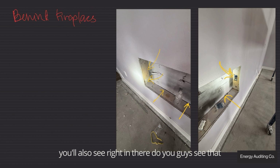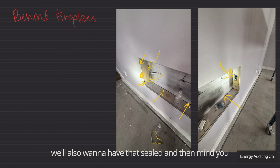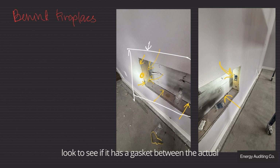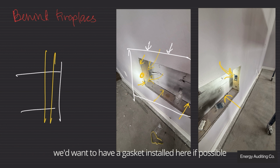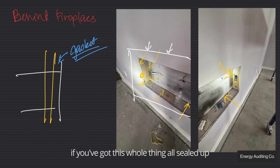You'll also see right in there, do you guys see that? Where those two materials meet, where the drywall meets the framing, we'll also want to have that sealed. Mind you, they're going to lay an entire fireplace over this thing. Look to see if it has a gasket; the fireplace probably looks something like that, and let's say our wall looks like this. We'd want to have a gasket installed here, if possible, if it comes with the unit. If not, don't worry about it. If you've got this whole thing all sealed up, we should be good.